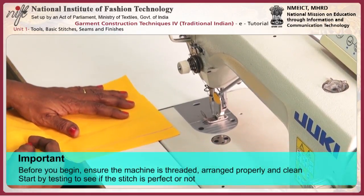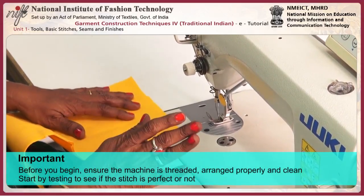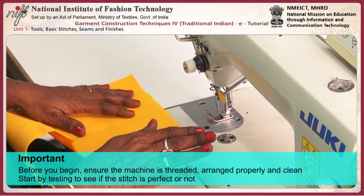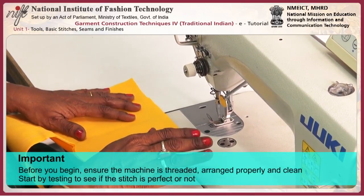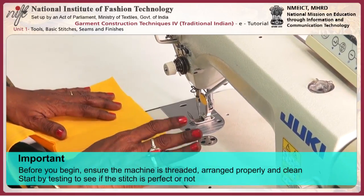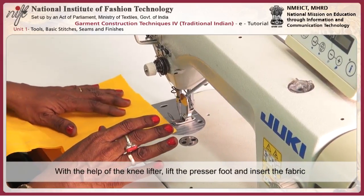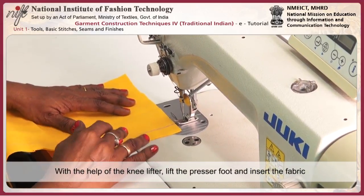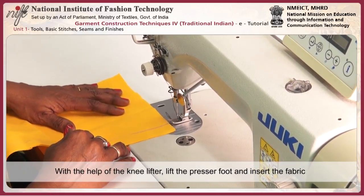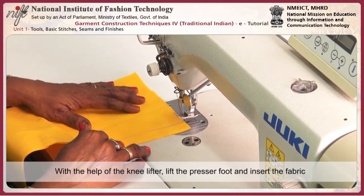The machine should be threaded and arranged properly. Wipe it cleanly, then start by testing whether the stitch is perfect or not. Make it ready to do your proper seaming. With the help of the knee lifter, lift the pressure foot and insert the fabric.